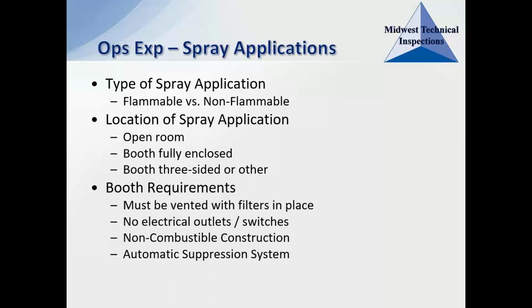But if it's a flammable to start with, like a paint, then you're just vaporizing a flammable and just asking for an explosion. If it's a non-flammable, well, even the vaporizing of it can cause some potential for explosion if there's enough of that vapor pressure, but it's not as likely. So it's a much safer process, so you need fewer controls in place for that non-flammable spray.